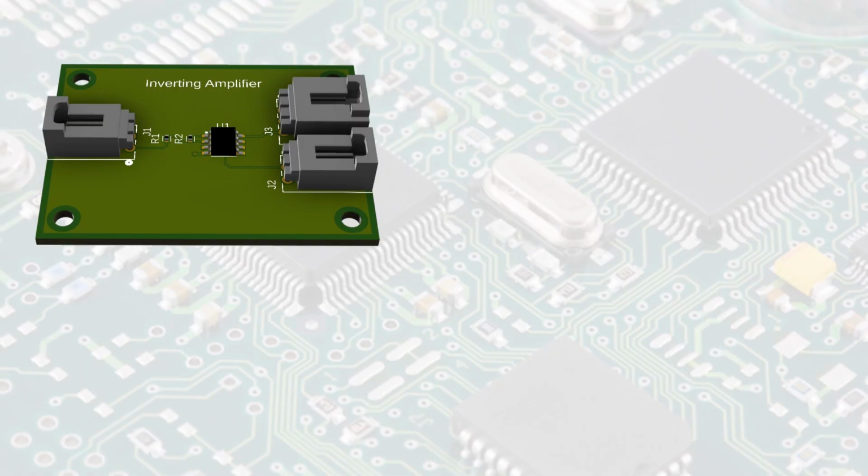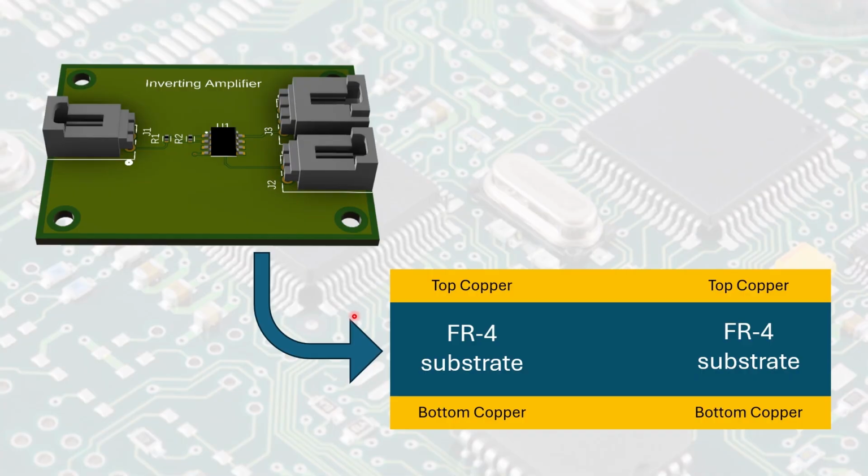For a better understanding of PCB manufacturing, let's first examine the anatomy of a double-sided PCB, one of the most common types of PCBs used in everything from prototypes and consumer gadgets to industrial electronic systems. The illustration below shows the basic structure of a double-sided PCB. At the core of the board is the substrate, typically made from FR4, a fiberglass reinforced epoxy material. The substrate provides mechanical strength while electrically insulating the conductive layers. In many ways, it serves as the backbone of the PCB.